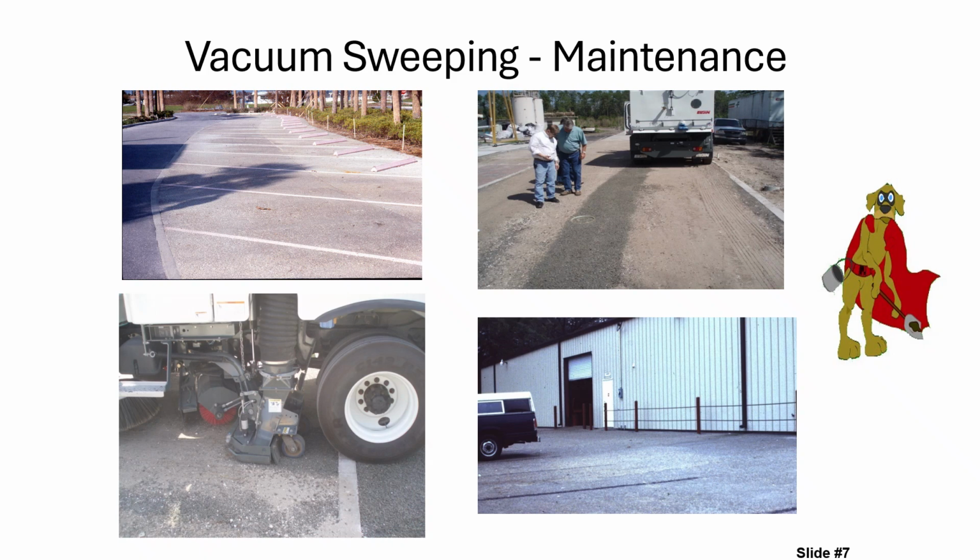One common method for assessing when maintenance is needed involves using an embedded ring infiltration kit, often referred to as ERIC. If, when using this kit, the limiting infiltration rate is measured to be lower than 2 inches per hour, it's a clear indication that maintenance is due. Alternatively, a more visible sign that maintenance is necessary is when you observe ponding on the pavement surface for over half a day. Among the various maintenance techniques, vacuum sweeping is frequently employed.